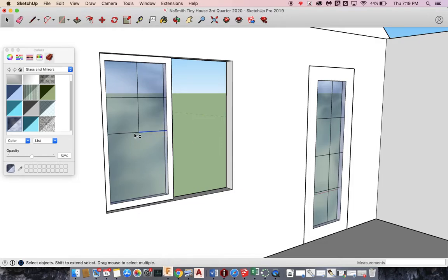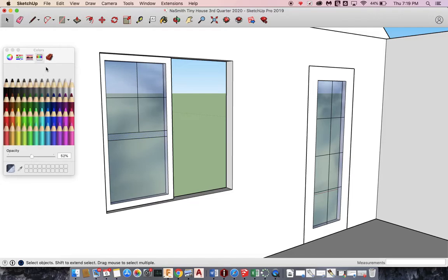One thing that's kind of cool, we can pick these lines and then use our move plus option key. So I have those bottom lines selected. I'm going to go M for move. I'm going to click it, and then I want to move my copy straight down. So I'm going to hit my up arrow key while I have that selected, and then I just want to make a copy of it. So I'll hit the option key. I'm going to come down 2 inches, enter. And now I'm going to make that back white like the rest.